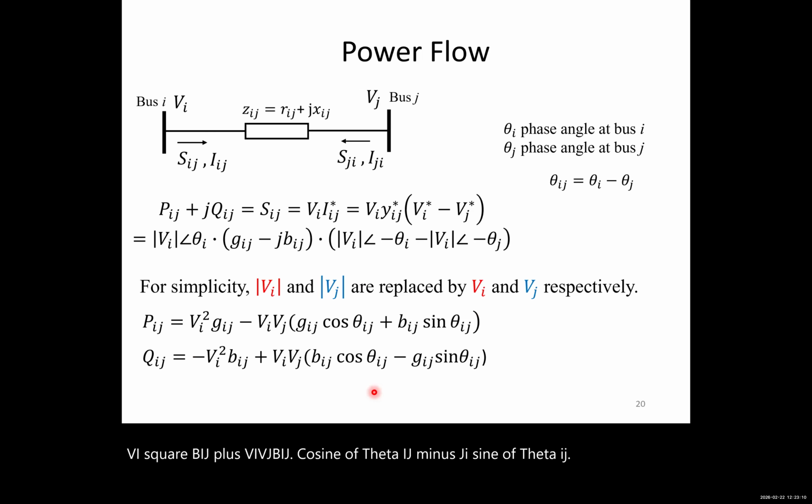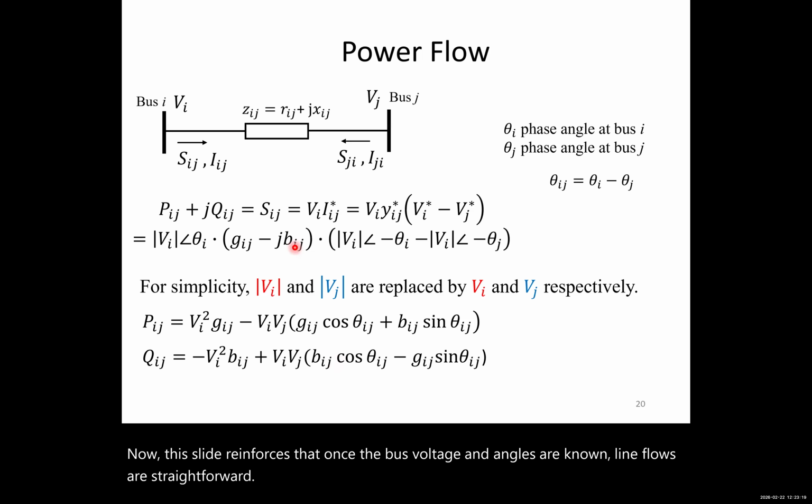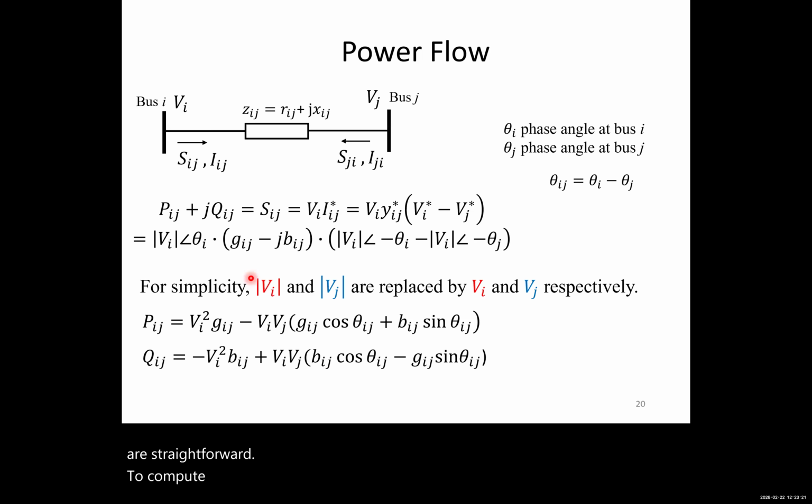Now this slide reinforces that once the bus voltages and angles are known, line flows are straightforward to compute. So the main computational challenge is solving for V and theta that satisfy the power balance of the bus.